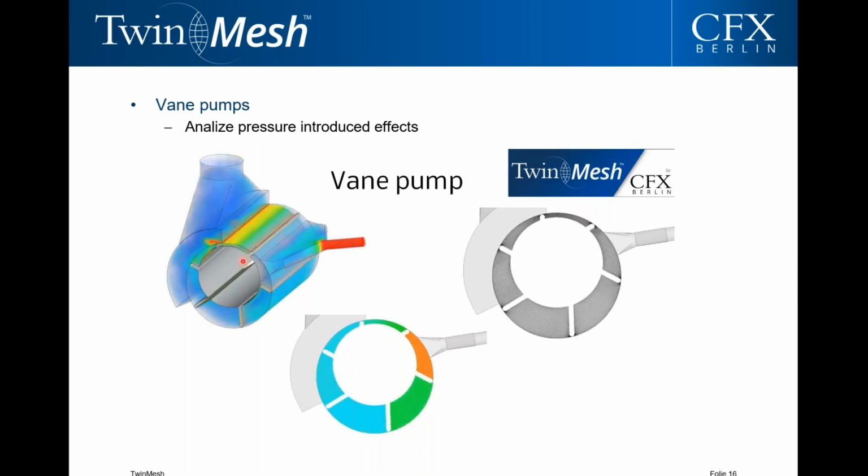And depending on when the vane passes the control edge, you can see that because of the pressure buildup, there is something like a bit of an overcompression, and you have this jet coming out of the chamber. This could be the basis of an optimization problem where you design the pump or the chamber volumes in a way that this does not happen.